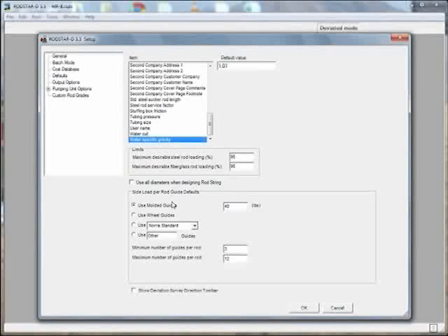You might select 1 inch as the maximum, 3/4 as the minimum. The program for a shallow well might use all 3/4 inch rods because the loading is going to be less than 95% here. Or it might use 7/8 and 3/4, but it may not need to use the 1 inch. Okay, so this section here, side load per rod, allows you to specify what rods you would like to use for the deviated program, and also what is the rating of side load per rod.